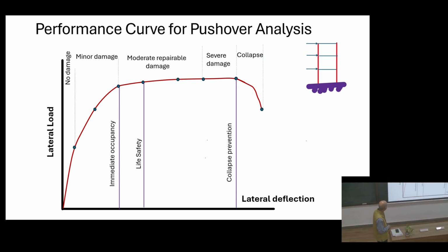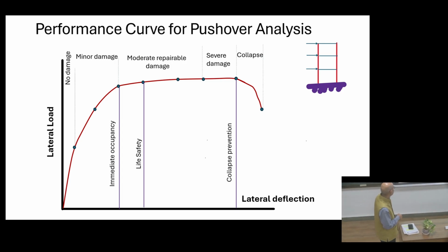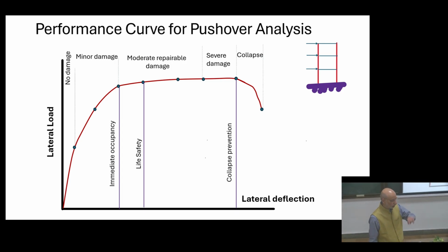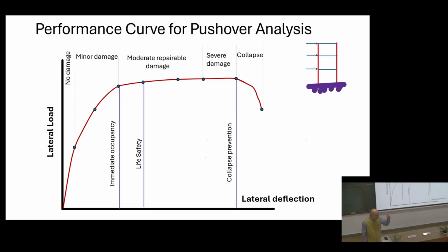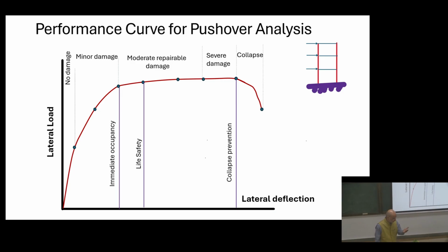So you say almost linear, and within this range, when you are at this level, no damage. Like earlier, when force-based design was there, still most of you are doing force-based design. Very few people do displacement design. It is mostly force, with a little difference; we'll talk about it later. What we do is divide by a factor of safety, called the partial safety factor, and we bring the load down and say this is your failure. So much strength you can reduce, and it goes down. That is the margin you build in.